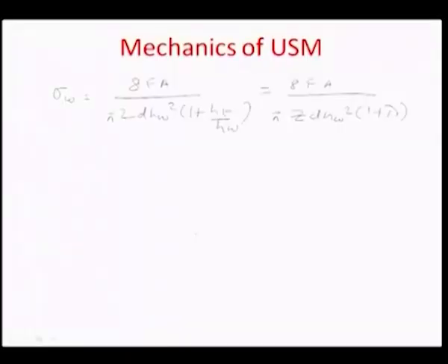In the process of doing that, we arrived at a formulation given here in this slide, where we were talking about the ultimate yield stress of the workpiece material, sigma W, and we correlated this to the average force that the vibrating tool head would give on the grains, the amplitude of motion of the tool A, and the number of grains or particles making impact per cycle.